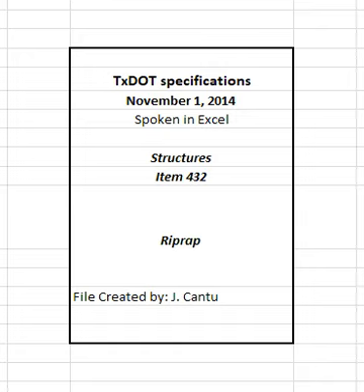Determine gradation of the finished, in place, riprap stone under the direct supervision of the engineer in accordance with ASTM D5519. Table 1. In-place protection riprap gradation requirements. See table in specifications.